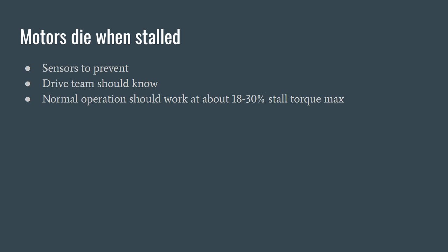Yeah. So that's actually part of the reason why you want to design around 20% stall torque, because the motor can generally sustain that for a very long time without dying. For figuring out how to fit this, honestly, I would probably just scooch these over and put this here.